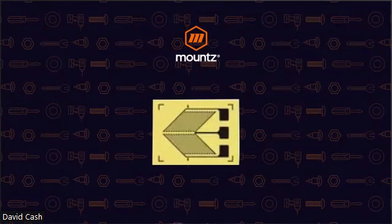And the strain gauge is a postage-size little sensor, maybe a little bit less than that, but it is an electrified circuit. And if there is any bend or if there is any tension put onto that strain gauge, we can measure the difference in the amount of resistance that happens within that sensor. And that allows us then to convert the torsional forces on the sensor to a digital signal.